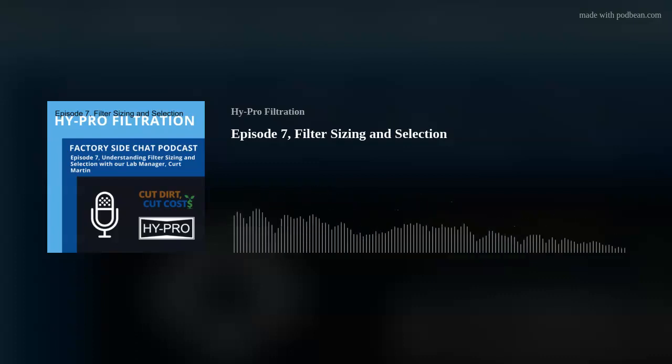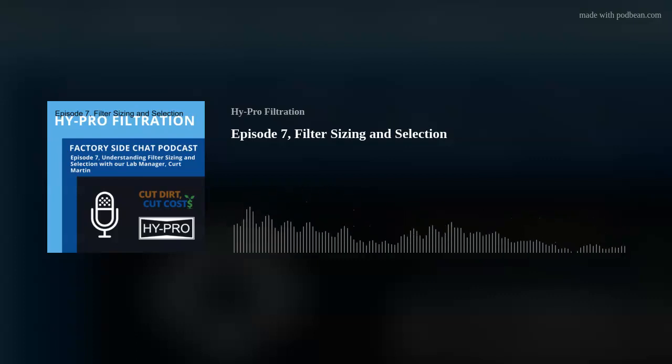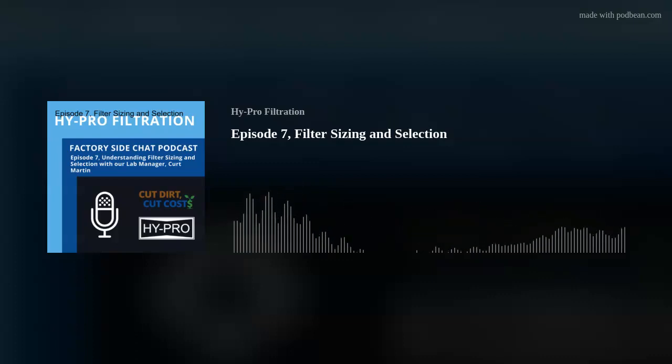What the collapse pressure, or the differential pressure of the element, is measuring is the upstream pressure minus the downstream pressure, and each element's going to have a collapse rating. So let's say 250 PSID, the D standing for differential pressure. What that is saying is anything below 250 PSID, where you take your upstream pressure minus your downstream pressure, the element's good, it's not going to collapse. Anything above 250 PSID, you run the chance of collapsing the element.